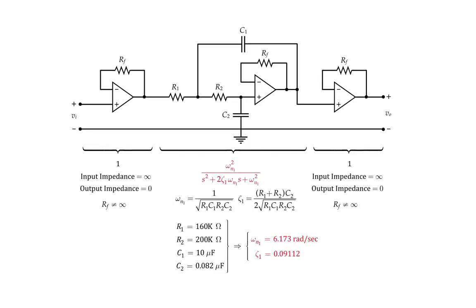Let's see here. Other things to note. The particular R and C values I chose give rise to a natural frequency omega n that's very close to 1 hertz and a damping ratio about 9%. So a lightly damped vibration mode at about 1 hertz for this particular analog plant. And finally, thinking about what it would take to, say, add damping to this lightly damped vibration mode with a feedback controller, based on the Nyquist criterion, you can easily calculate that the absolute minimum sampling rate would be roughly 2 samples per second.